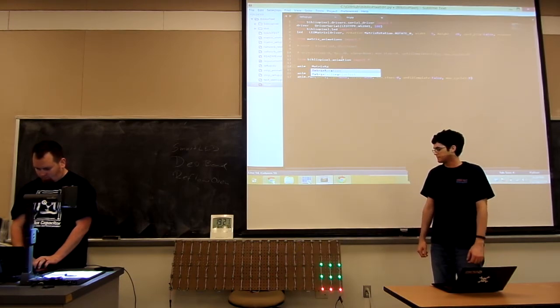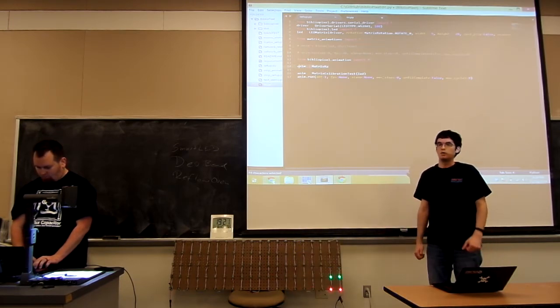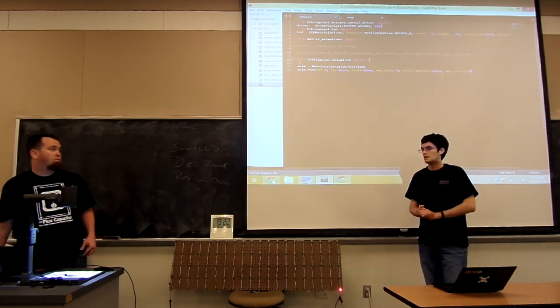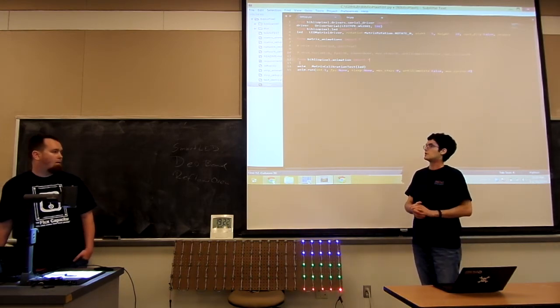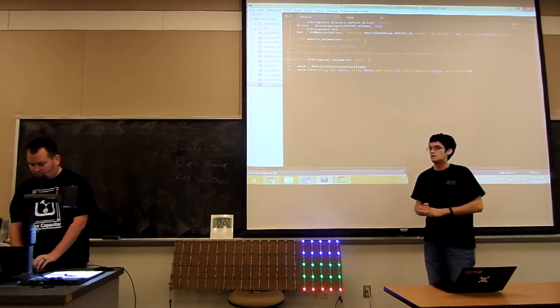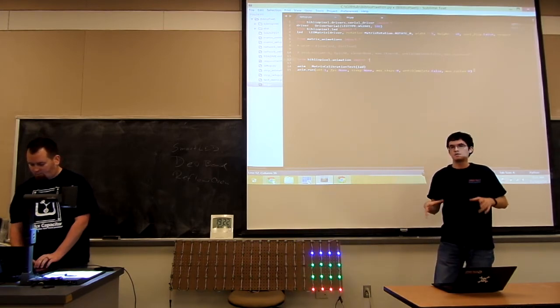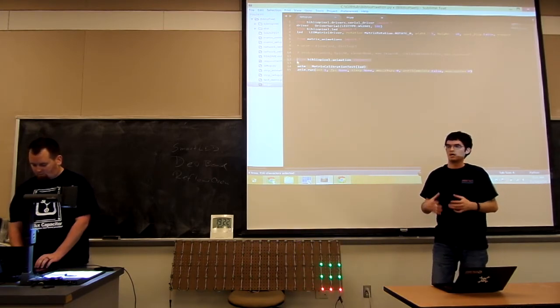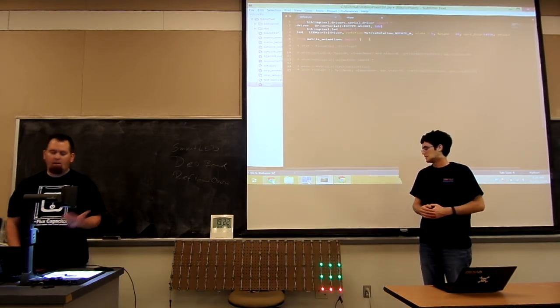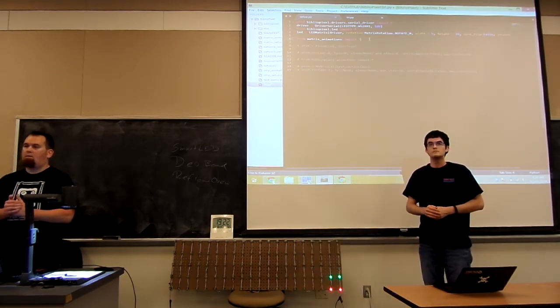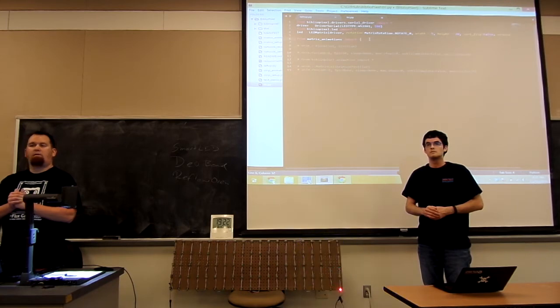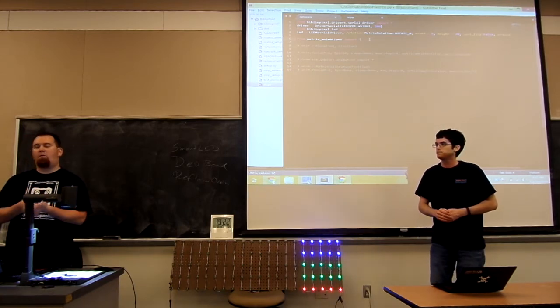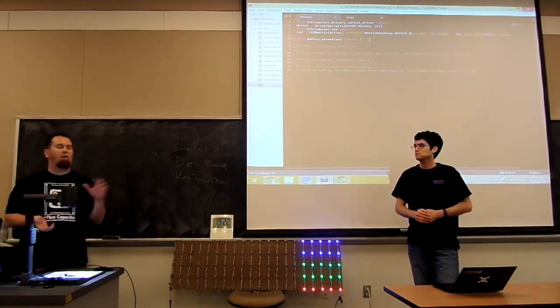Which flavor are those? These are the WS2801 style chipset. So if you were to configure it in here, or if you were to just use the software library somewhere else, you would want to make sure you're using that correct protocol for it. Is the 2801 the SPI one? It's standard SPI, limited to 1 megahertz. That's sort of one of the downsides.